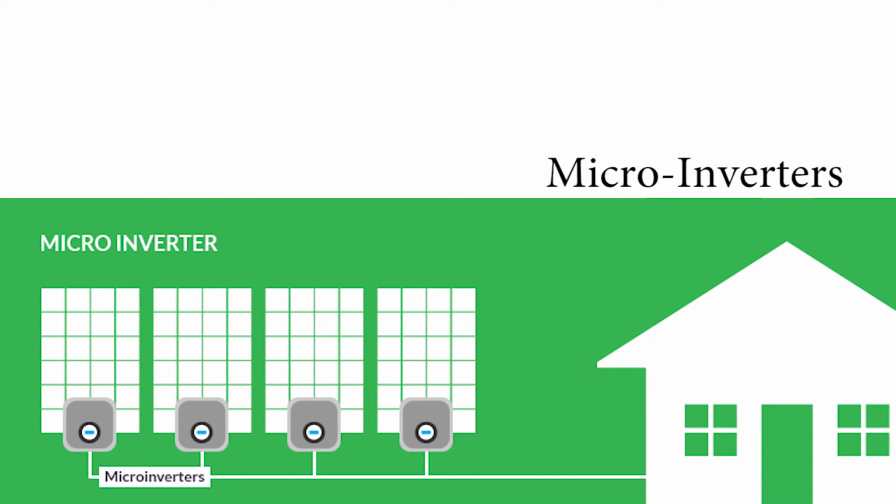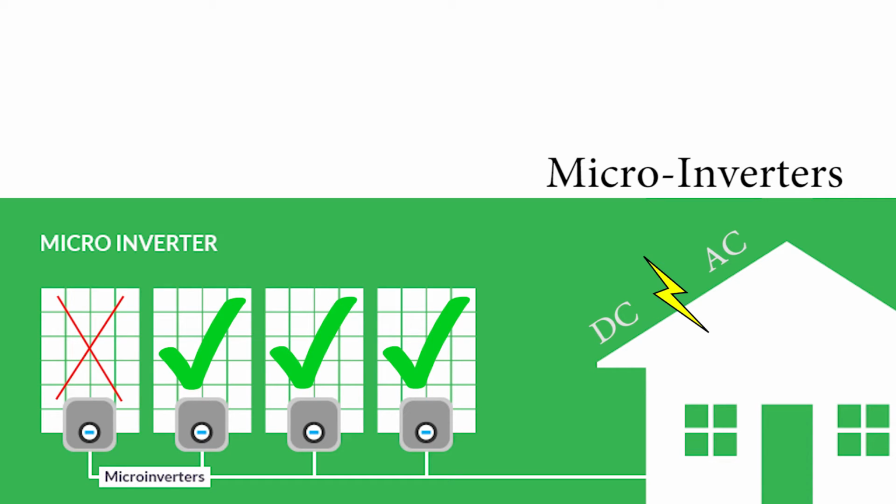Microinverters tend to be more expensive, but they have their benefits. Microinverters are installed at each individual panel, so they convert DC into AC right on your roof. A major benefit to this system is that one panel will not affect another, so you would want this system in shady areas. In addition, you can monitor the performance of each panel individually. Another benefit is that you can connect more panels as your energy needs increase.